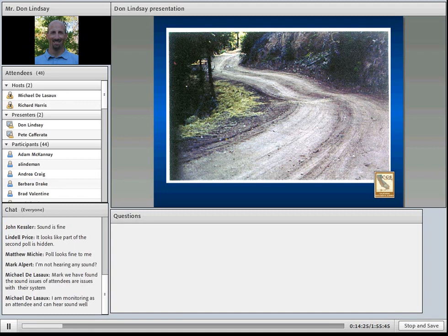This is an example of an outsloped road with a rolling dip. Outslope roads direct runoff from the cut bank across the road to the fill slope. Outslope roads have the smallest area of disturbance, are less prone to intercept groundwater, generate the least amount of fill that would be prone to erosion, and are often the cheapest to construct and maintain. Outslope roads should not be used on steep road grades in highly erodible soils or where slippery conditions are anticipated.